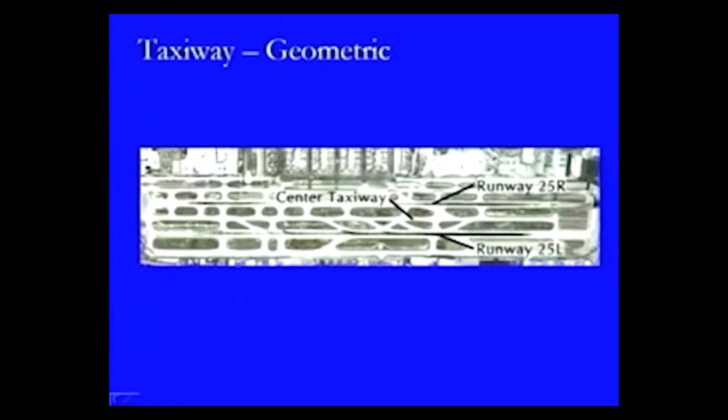This is another photograph being taken from the top, where there is a runway strip being defined here like this. This is one runway strip, and there is a parallel runway strip being provided at this location. So, we have the two parallel runway strips being designated as 25R and 25L. This 25R means R for right and L means for a left condition.